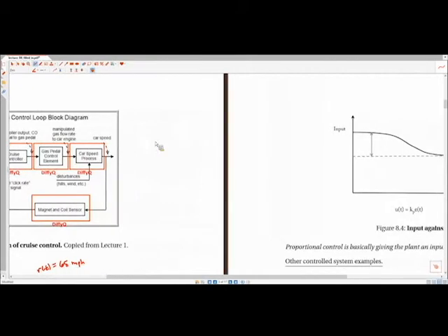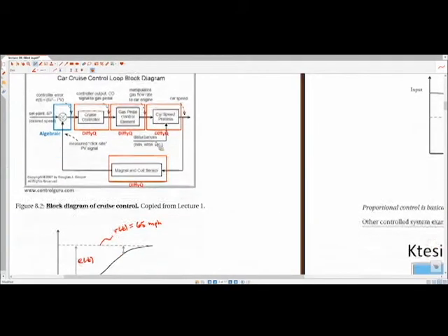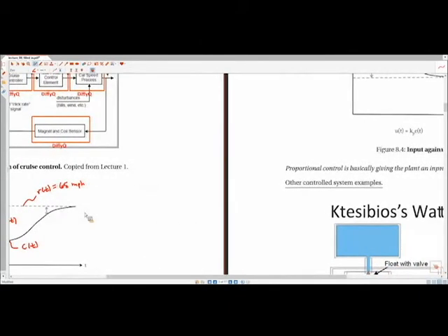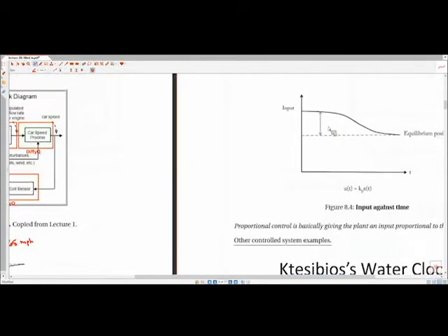So this is proportional control. We'll get into proportional integral derivative control later, but it would say, okay, let's make the change in angle of my accelerator proportional to the error. So if the error is really large, I want to make the input really large to counteract that large error, and as the error gets smaller, then we can decrease this input to our system because we've reached our goal, right? That is the general idea behind cruise control.